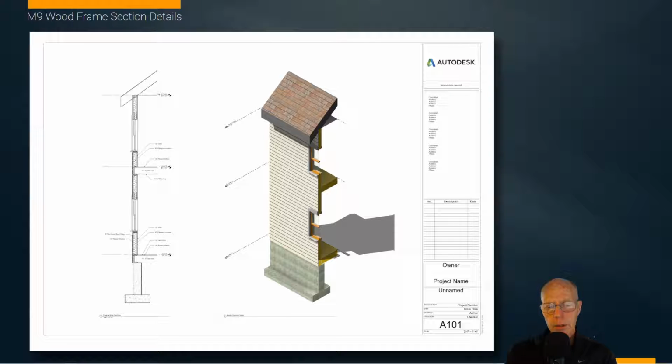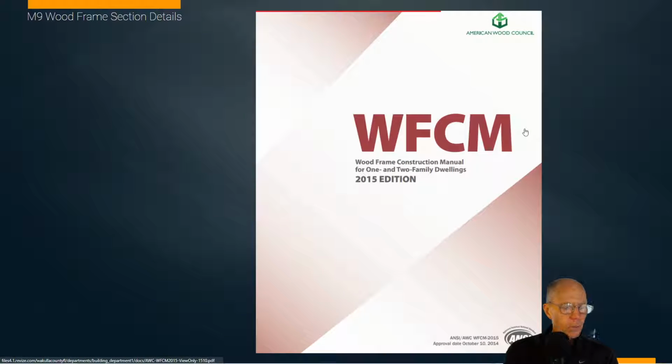So once again, I can't really zoom in here, I've inserted the windows in, but all of these little details, these two little top plates, the header over the window, all of those things are graphically inserted into our illustration. They don't actually exist in the model space. So these are things that we have to go back and add in order to communicate accurately how this wall is constructed. So I hope that's a good start for getting you in the mindset of doing these kind of section wall details, which will become a really important part of what you do as an architect to communicate it.